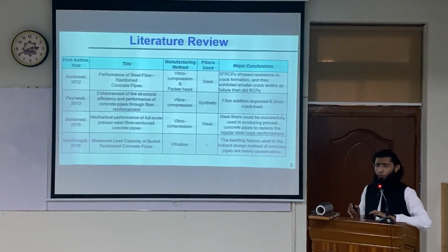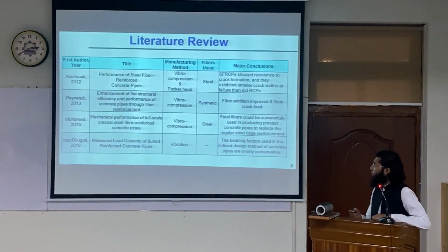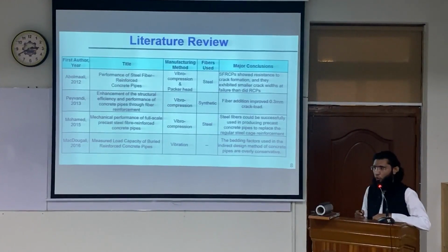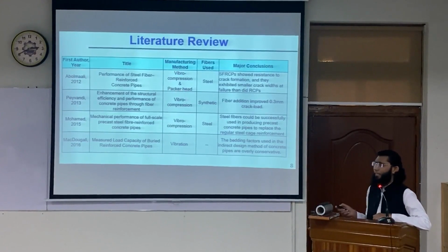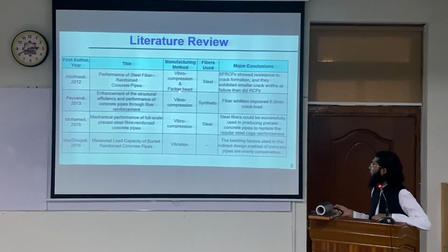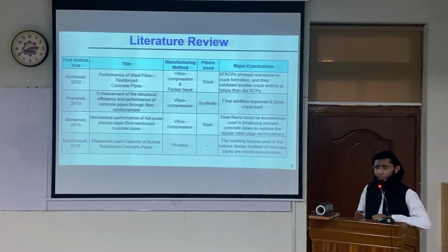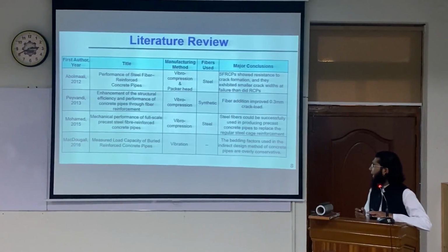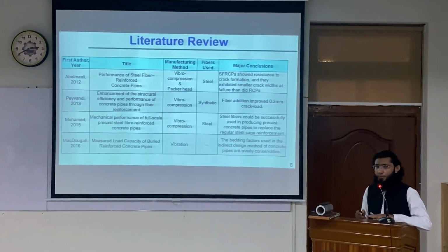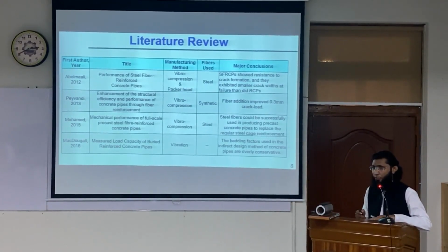This is a quick overview of the literature that I've reviewed. Several researchers have attempted to study the performance of fiber-reinforced concrete pipes manufactured using either the vibro compression method or in some cases the packerhead method, and the investigated fibers are either steel fibers or synthetic fibers in mono form, and most of the results conclude that fiber-reinforced concrete pipes can be an attractive alternative to the traditional reinforced concrete pipes due to superior crack resistance.